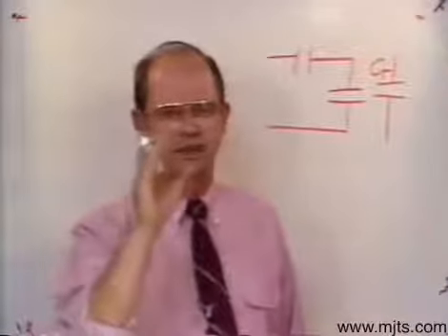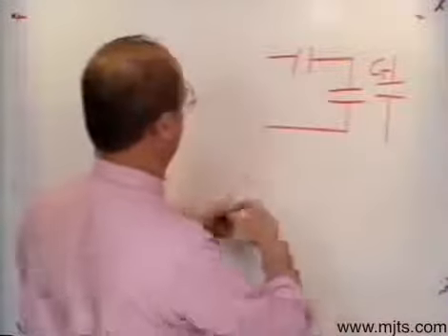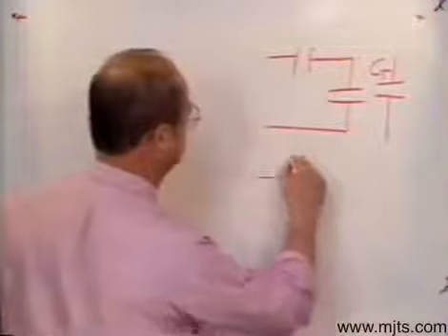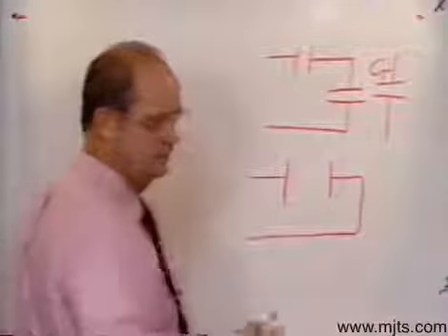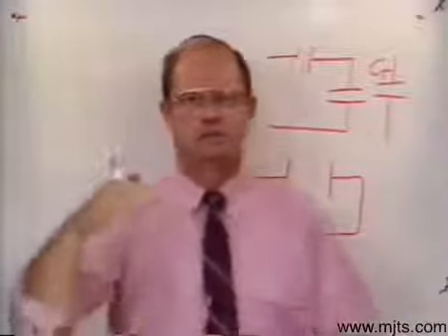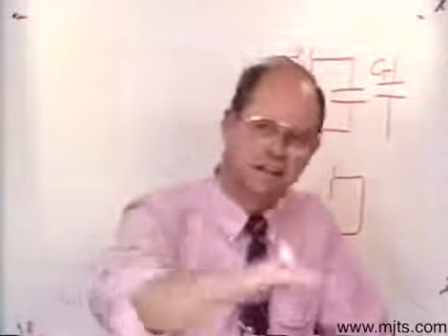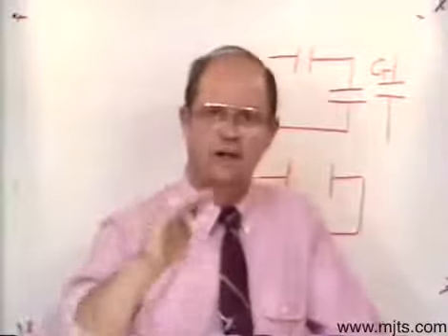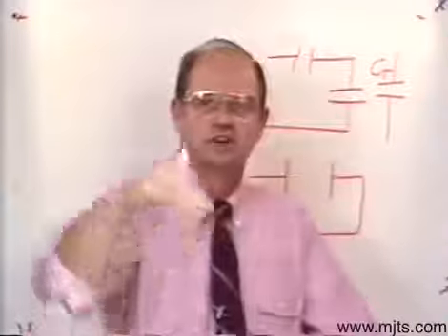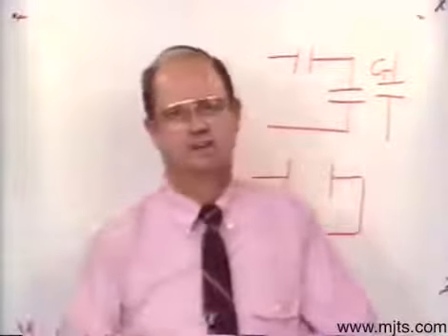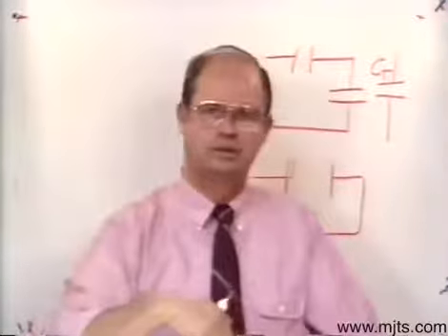And the reason for that is when I put them in series with one another, it's like one capacitor with twice the distance between the plates, is really what happened. So if I put them in series, I'm going to have less capacitance. If I add more capacitors to the circuit in series, I'm going to have less. It's actually an inverse effect. More capacitors in series are going to have a less capacitive effect.